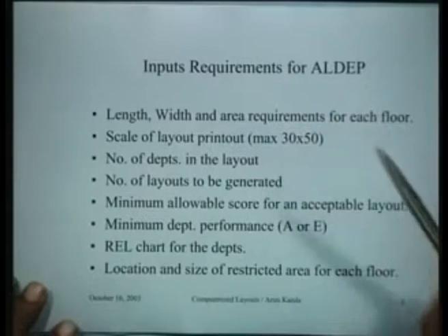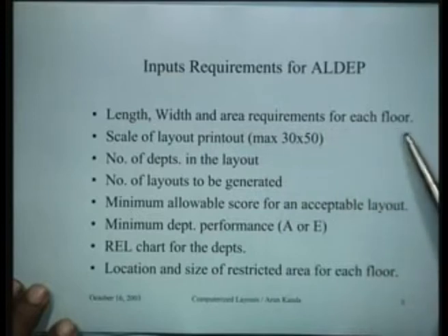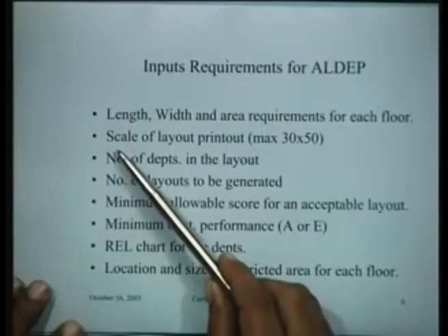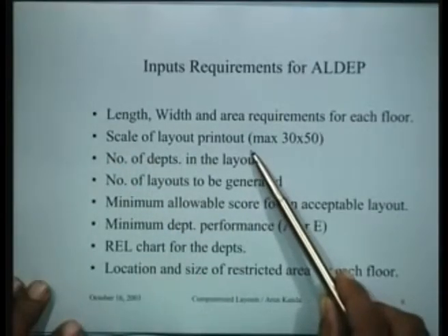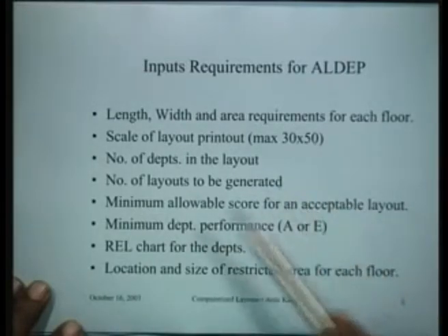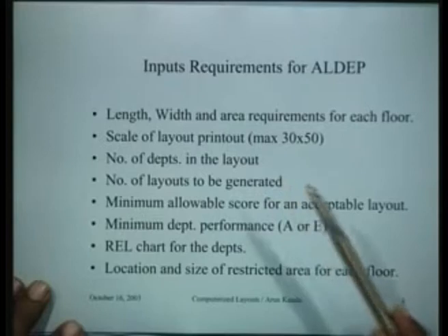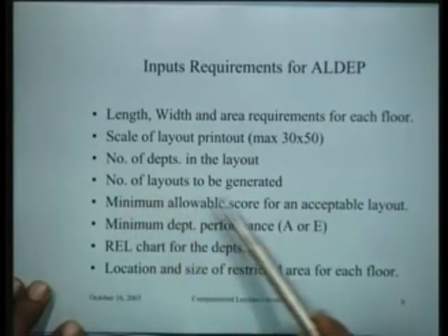So here are the input requirements for LDEP. What is the input needed? You need the length, width and area requirement for each floor on which you are going to do the layout. As I indicated to you, LDEP has a provision for handling layout problems on 3 floors. So you have to specify this information. You need to specify the scale of layout printout, which is generally a maximum of 30 by 50. You have to specify the number of departments in the layout. You have to specify the number of layouts to be generated.